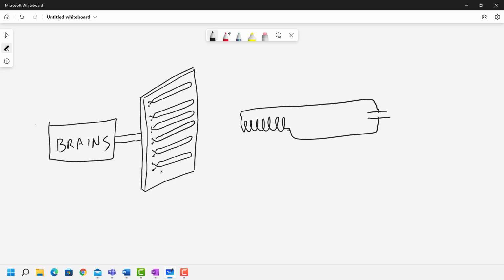Now what's happening here is that each one of these coils can deliver power to the nearby pen. Each one of them can listen to the pen. Let's suppose the pen is close. The fact that these coils are arranged along the x-axis, but they're going up and down, means now we can detect the vertical position of the pen. Because if it's at the bottom, then this coil will register strongly that the pen is near.